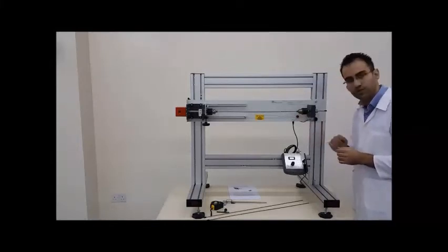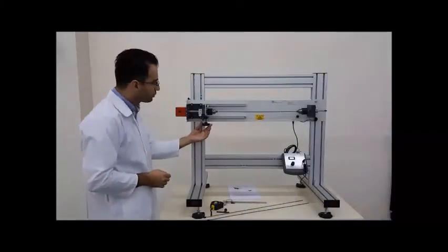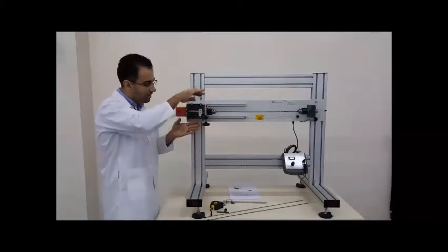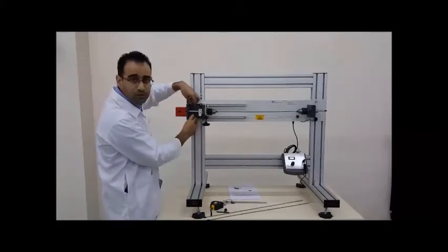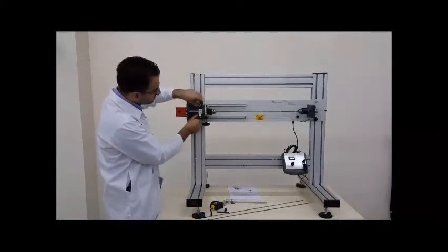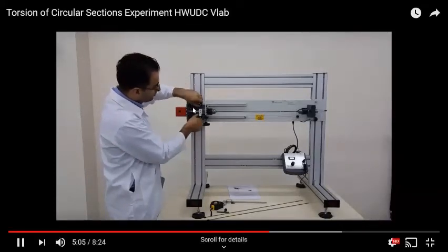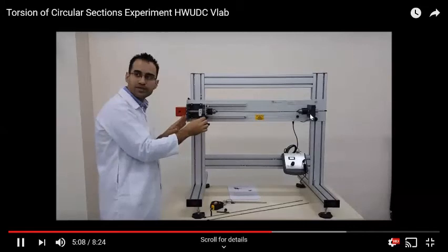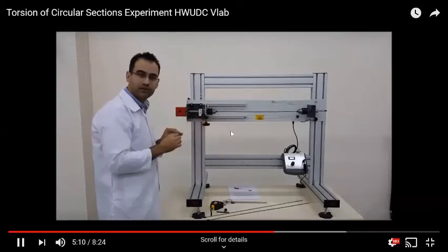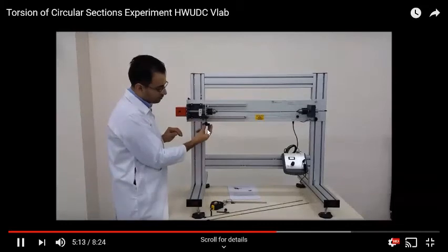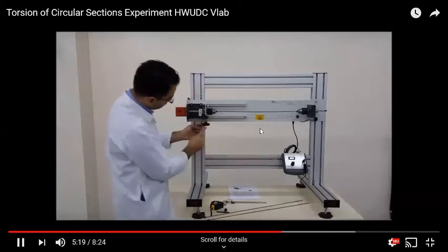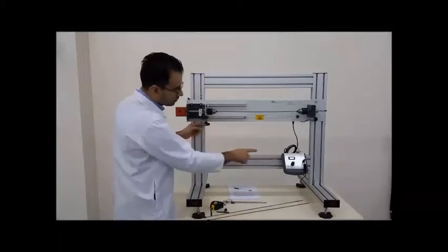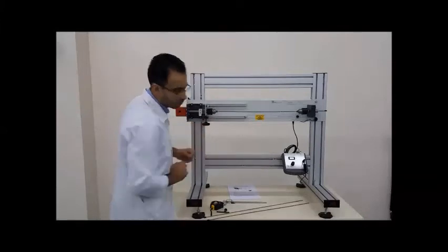So now you have 0, but there might still be slack in the equipment, in the rod and the equipment. So you always want to make sure you put some small torque on your rod and then go back and 0 everything. So he's now tightening all these bolts. He's still keeping his 500. And then he's going to start applying a small torque to the rod just to make sure everything's engaged. It's a small torque, and I think it's in your lab manual, maybe 0.05.